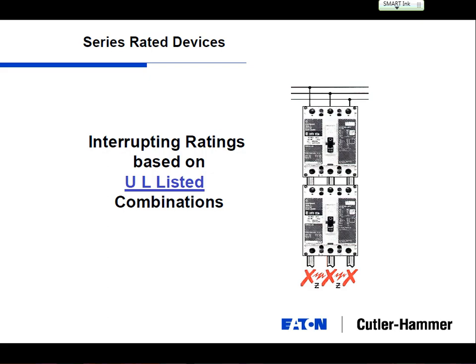If you think about a hospital, why that's important: when the generator kicks on and you're running emergency power, and you've got 3 operating rooms going with surgery or some type of procedure, and somebody trips a breaker, maybe accidentally put in too much equipment and overloaded the circuit, you really need the device on that specific circuit to trip.